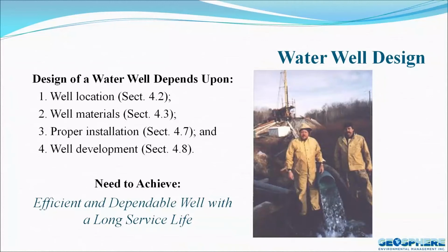The design of a water well is not cookie cutter. It's not, we'll do it here like we did it everywhere else. Each one is unique. Just as each person is unique, each well is unique. Some of the key factors that go into developing a well, and Ted alluded to some of this in his presentation, are the location of the well. Where are we going to put this? What's the formation like? Is it coarse grain material? Is it finer grain? What's the transmissivity of that material?